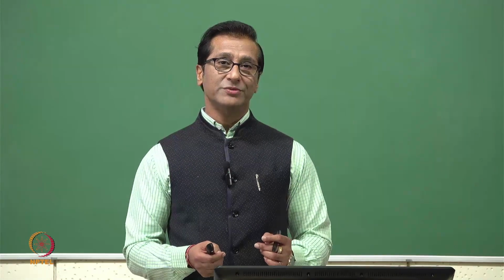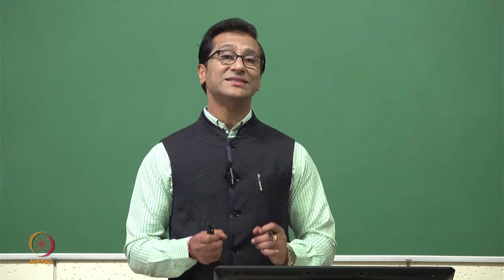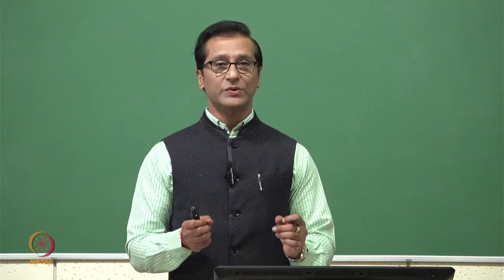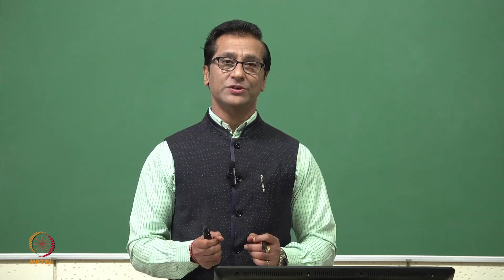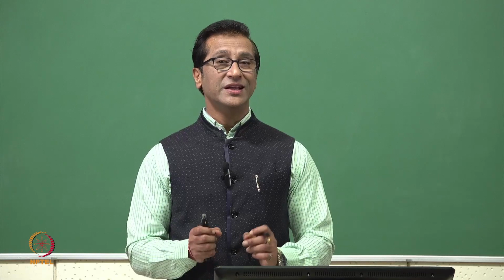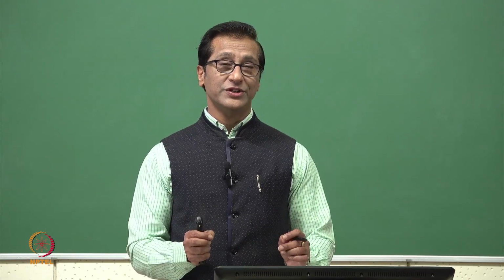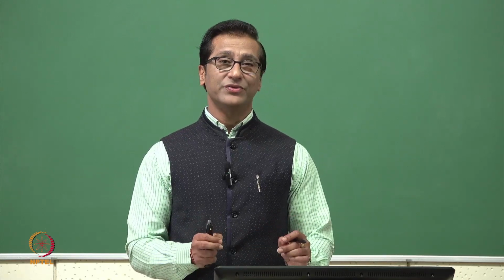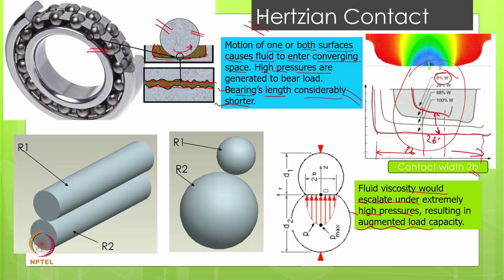With elastic deformation, load carrying capacity is enhanced significantly, and that's why we want every tribological surface to run in elastohydrodynamic lubrication. It gives a minimum coefficient of friction, and it gives minimum wear also. Now we have considered spheres. In this case, sphere 1 and sphere 2 have been shown. However, it can be roller 1 and roller 2 also, and then we can derive the expression.